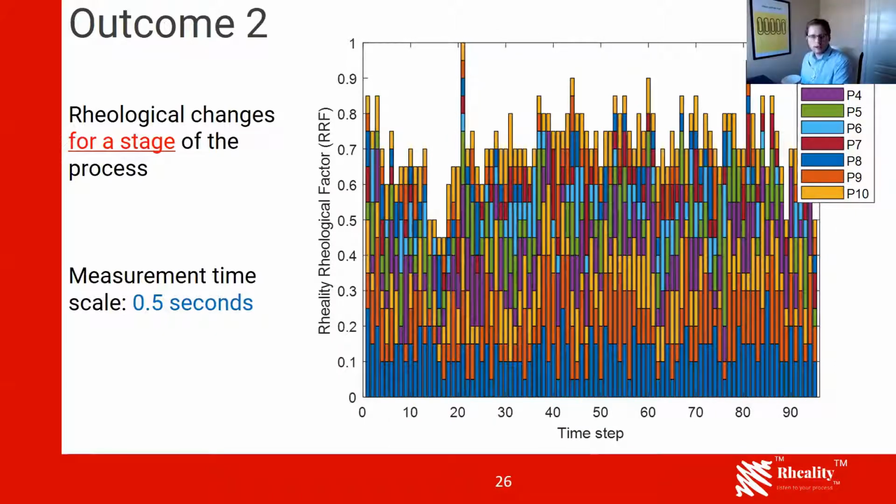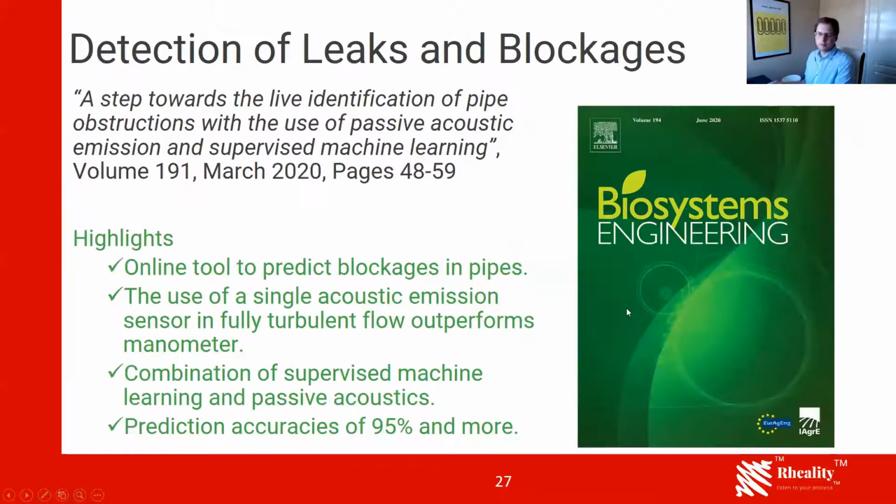We can also look at a very, very short time scale. The measurement time scale is half a second, and just looking at one stage, we could see how the product is actually changing during the mixing stage, just the very same product in the same process. And if we continued this, we could then identify the point of steady state, so they could move on to the next process stage.